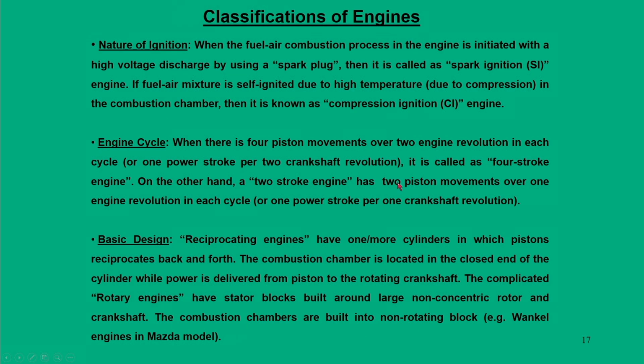Then we talk about the classification of the engines. One is the nature of ignition. Nature of ignition means that when the combustion has to be initiated within the engine cylinders, there are two ways to do it. One is to manually create an ignition, the other is to allow the charge to ignite spontaneously on its own. Based on that, we call these spark ignition engines or compression ignition engines.